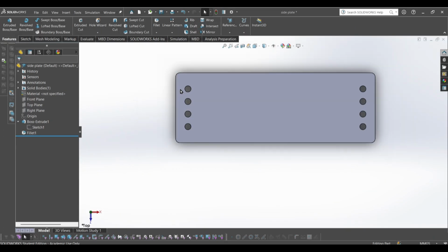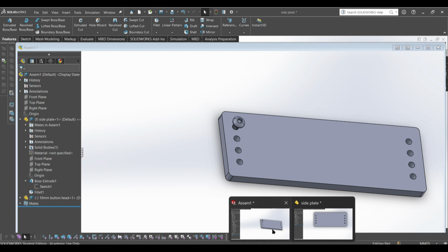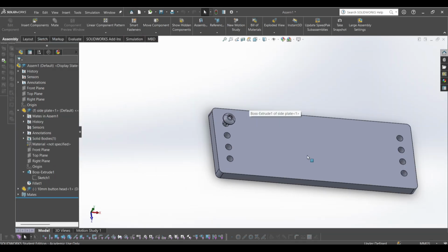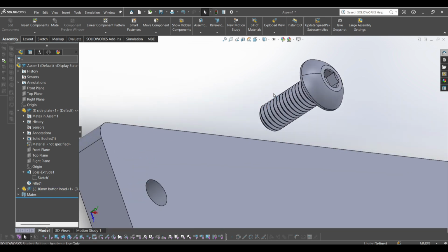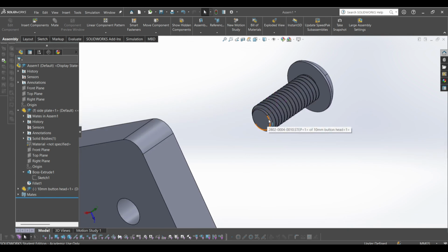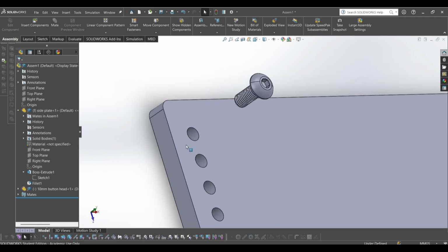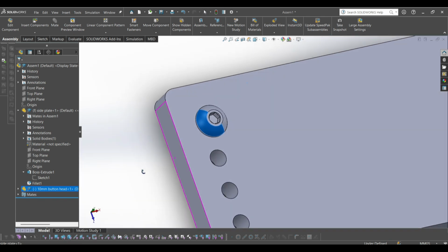Understanding tolerancing is kind of the first step where you're bridging actual CAD and FTC with assembly, because you're considering how your CAD is going to affect how you assemble something. And I'm going to show you guys an example of that. So right now, imagine that you're trying to put this screw through a hole in the plate. The diameter of the screw over here is 4 millimeters, and right now the hole on the plate is also 4 millimeters.